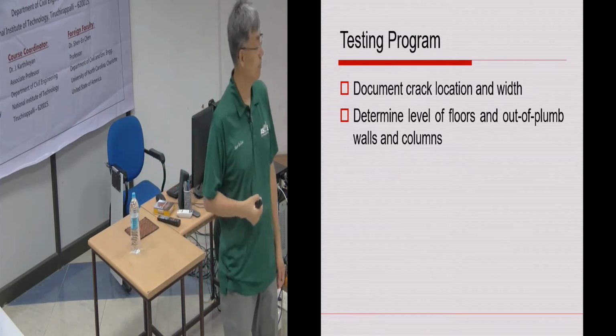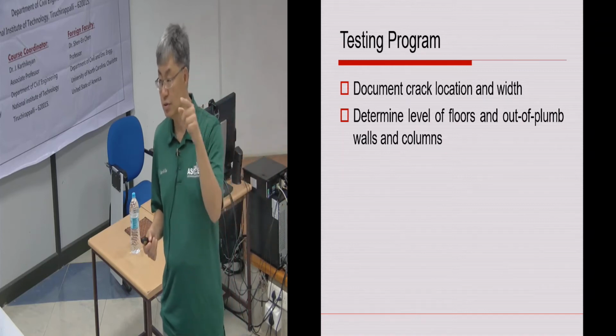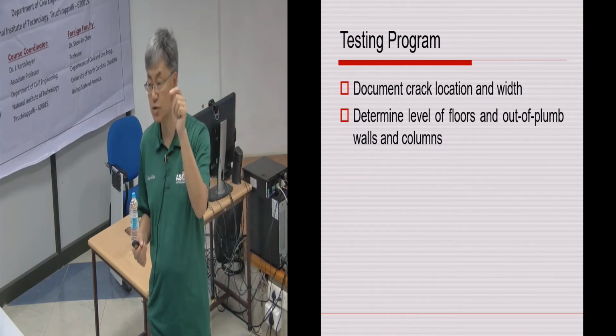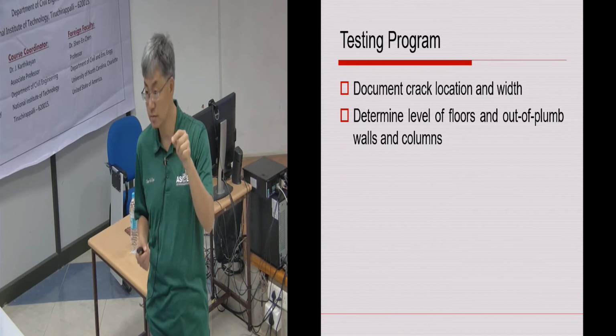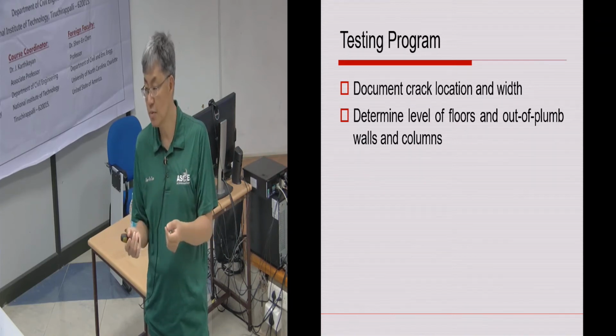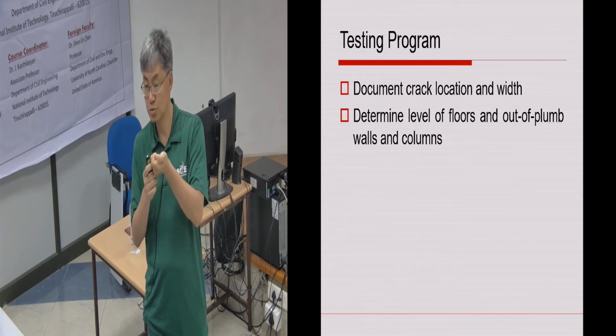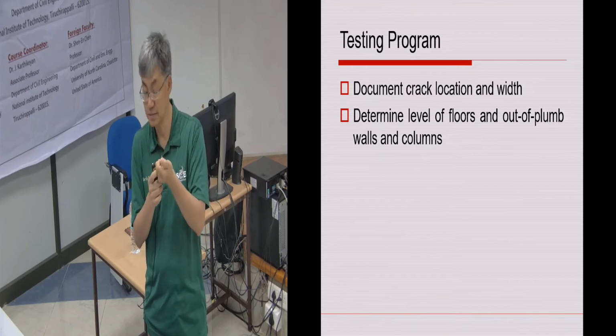Testing program, okay? So you need to know where the damages are, and then you need to be able to do some in situ tests in the field. For example, when we say testing, you may be using a Schmidt hammer to tell what the strength of the concrete is on site.